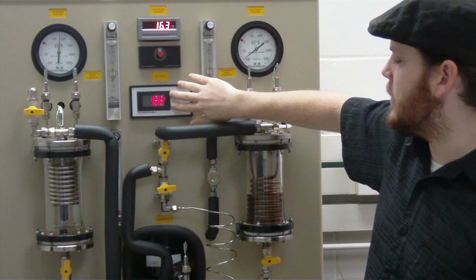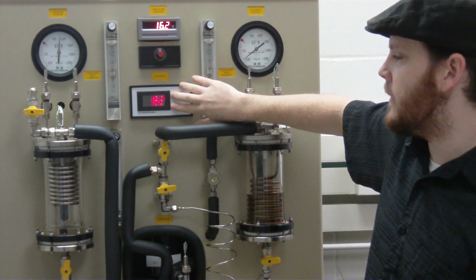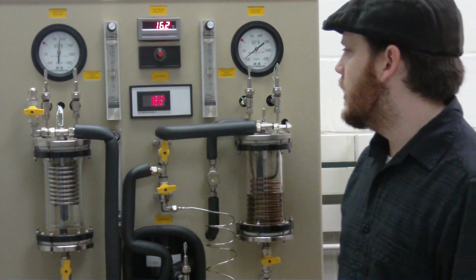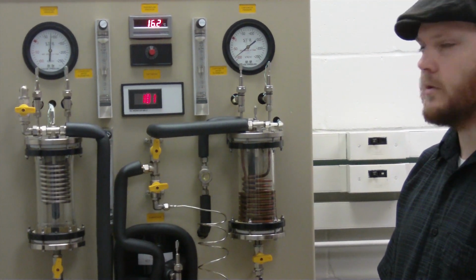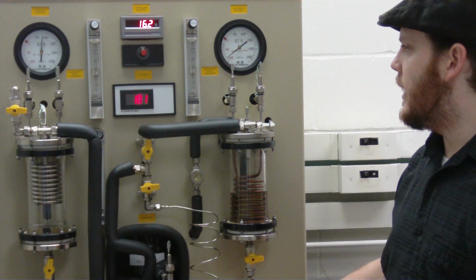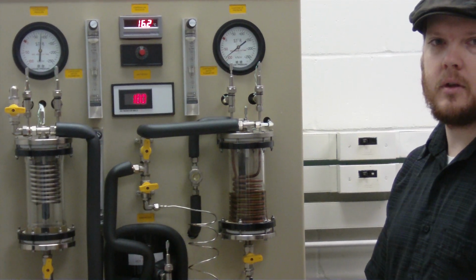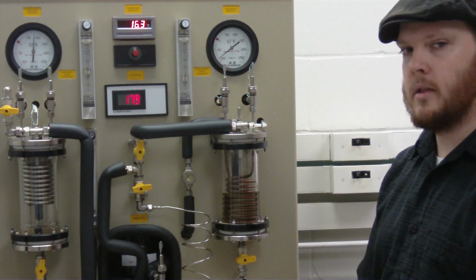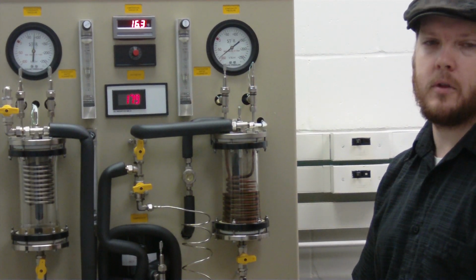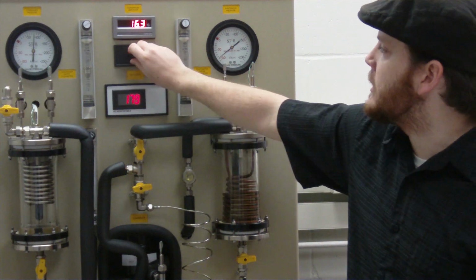And the power being used by the compressor reads out right here in watts. You want to measure all of this before or during the lab once it's reached a steady state, and then following the directions, adjust the level and wait another 15 or 20 minutes for it to reach that state before taking these measurements again.